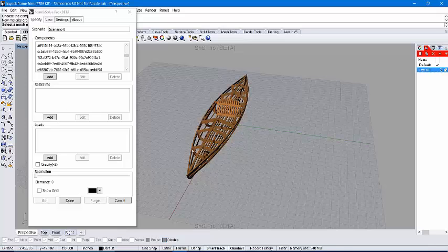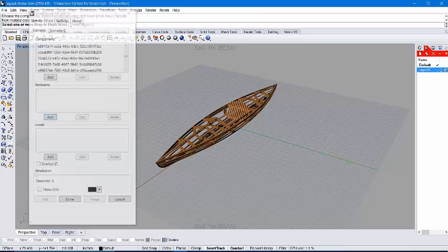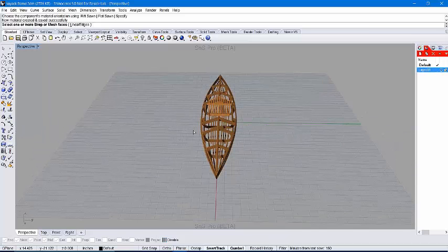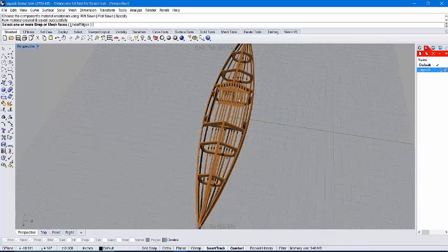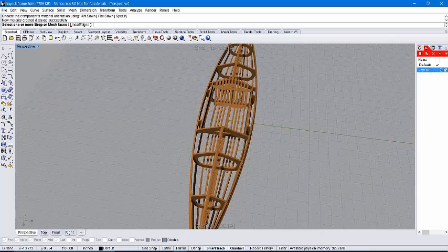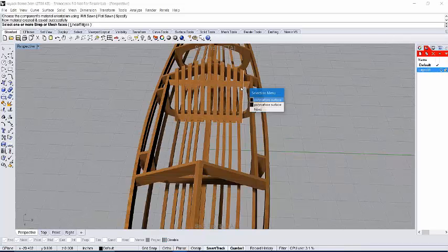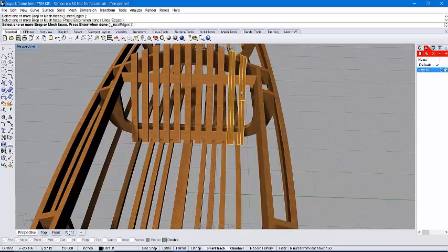So now it's time to add the restraint. So you have to think about where you want the restraint to be added. When the skin is applied, it will be covering almost all of the kayak, and the force will be distributed almost on all of these surfaces. However, the seat should remain unaffected. So I will go ahead and add it to the seat as my restraint. No force should be transferred to the seat, and no deformation should be experienced.